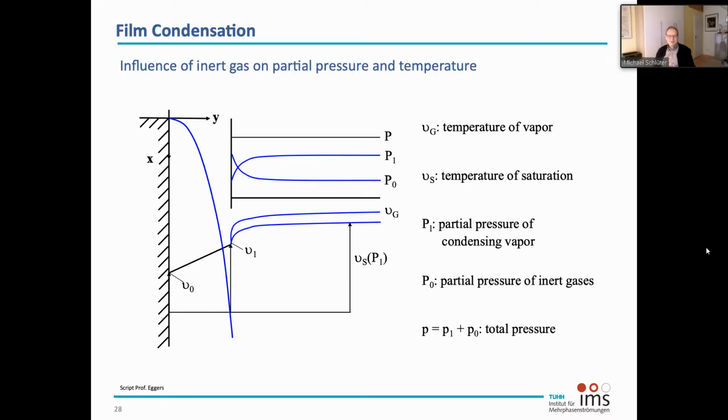And the reason for this might be that you have non-condensable gases. So what does it mean? I already mentioned you have the condensation film, the condensed film here. So this means, due to the condensation and the decrease in volume of steam, you have a lower pressure at this condensation site than in the bulk flow. So this is the overall pressure, and the pressure of the steam decreases here due to the volume decrease. Yeah, I guess this is not very surprising.